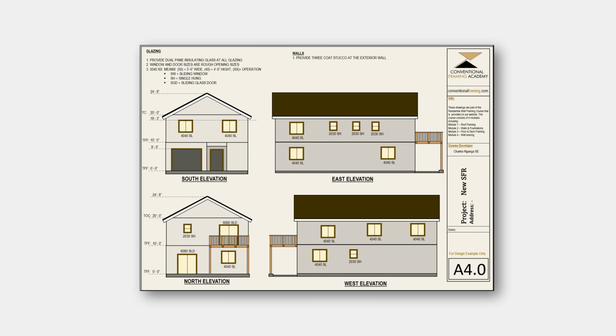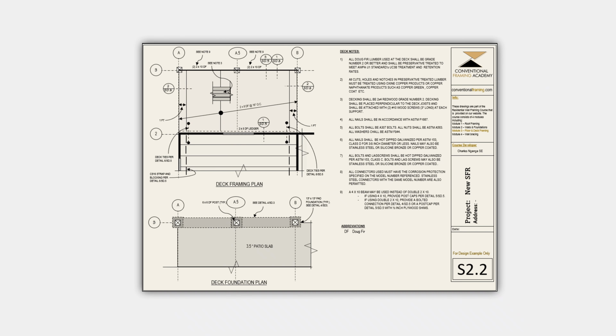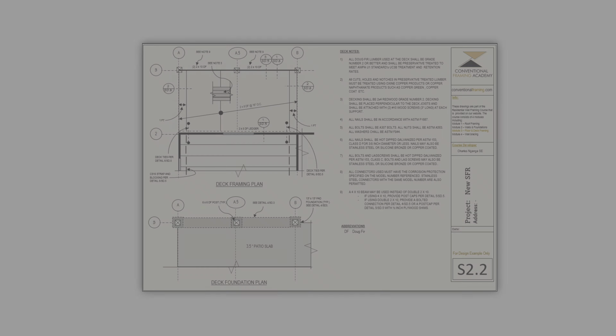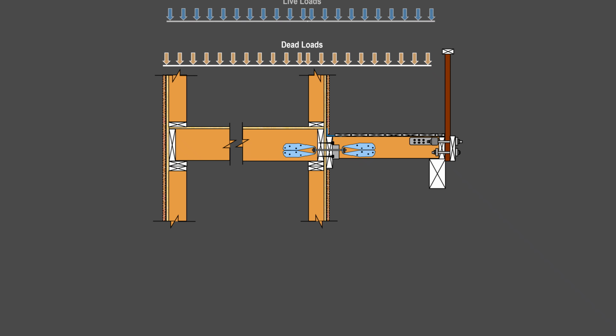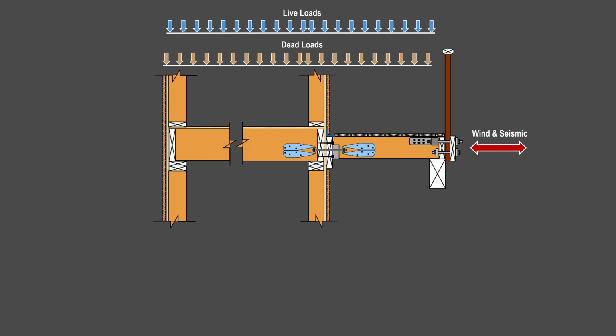The plan review process for floors and decks begins after the reviewer has determined the weights of the elements that are supported by the floor framing members. The structural design of floors and decks consists of the development of a system of structural elements to resist gravity loads such as dead loads and live loads as well as lateral loads including wind loads and seismic loads.